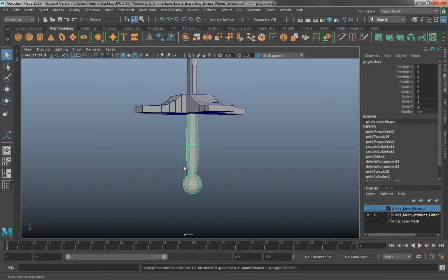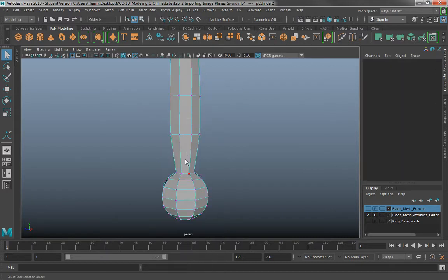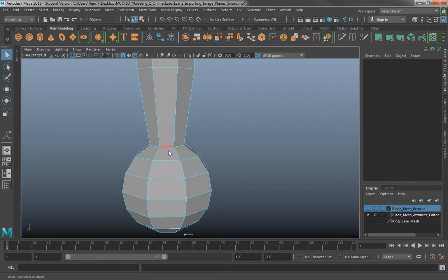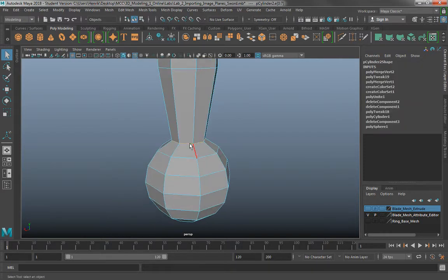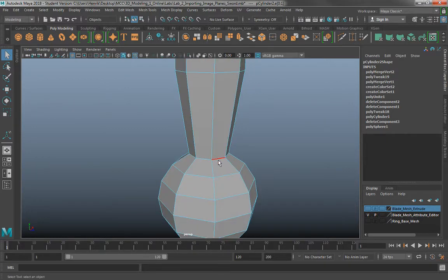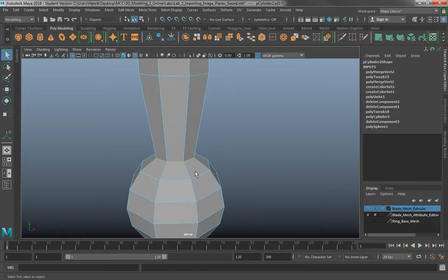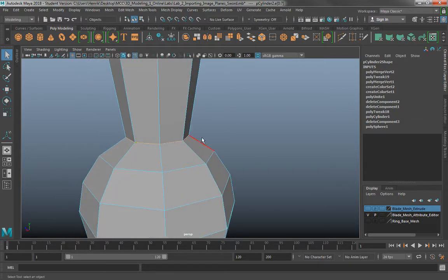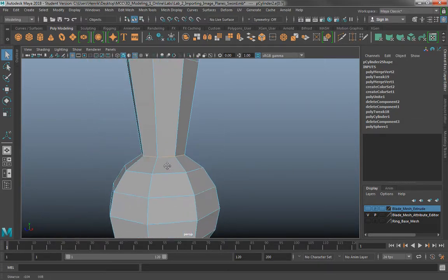Now, going back here, I'm going to select my Edge tool, and this is a really neat tool. Sometimes it doesn't work correctly, in which case I'm going to show you another way to do the same type of operation using a different tool. But this is a really cool tool. I'm going to double click this edge. It's going to highlight this entire edge loop. This is called an edge loop. If I double click it, as long as it's a closed object and all the vertices are merged, it will select them all around in a sequential order, circulating the mesh.